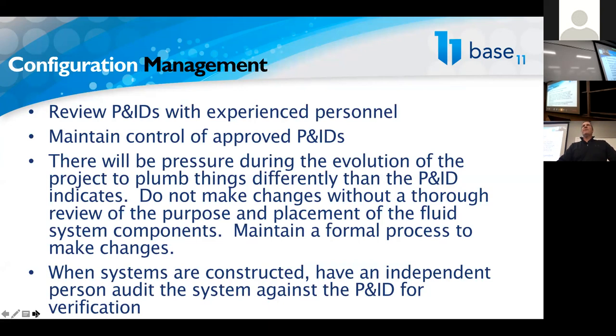Once you make your list of components, we do that in a spreadsheet. We basically have a column for what I just called valve 1, 2, 3, 4, 5, right? What we have evolved to is a valve numbering scheme where, if it's a manual valve, the first designator on the valve is MV for manual valve.